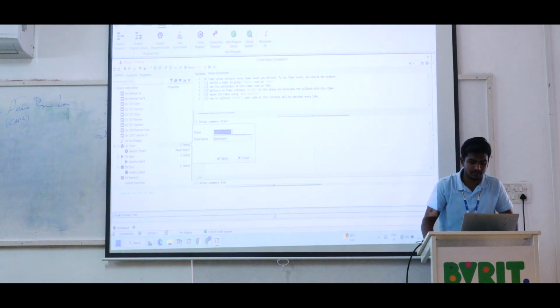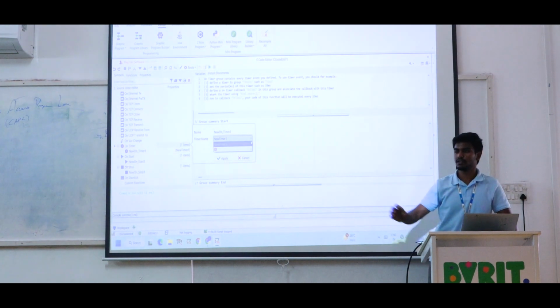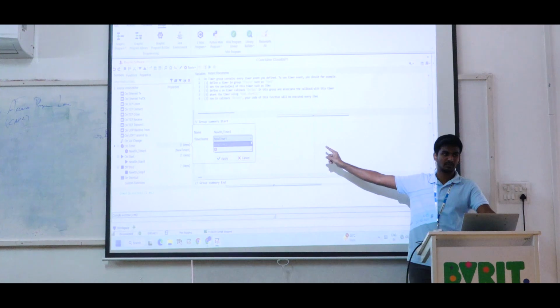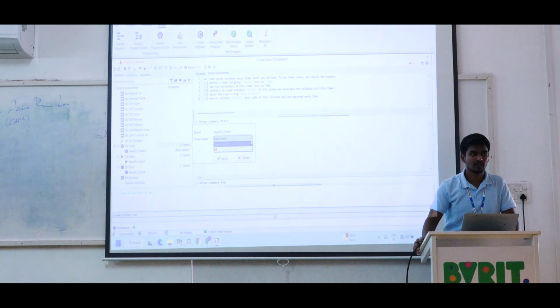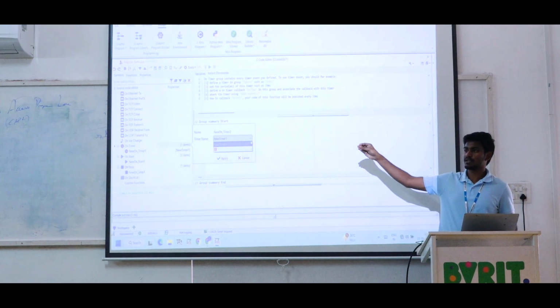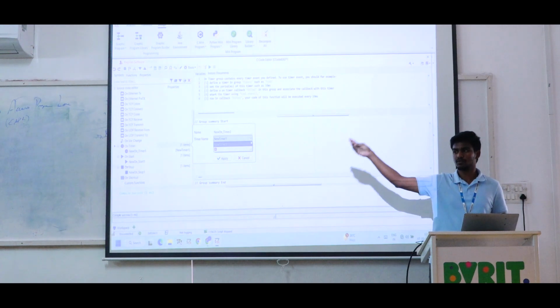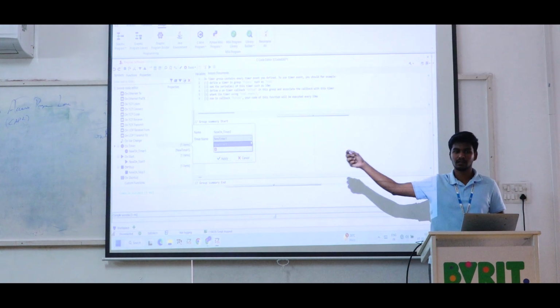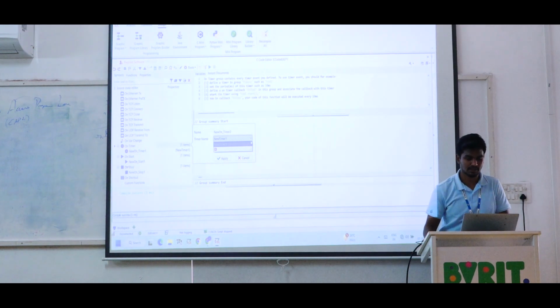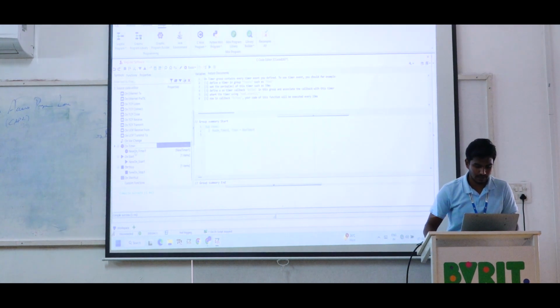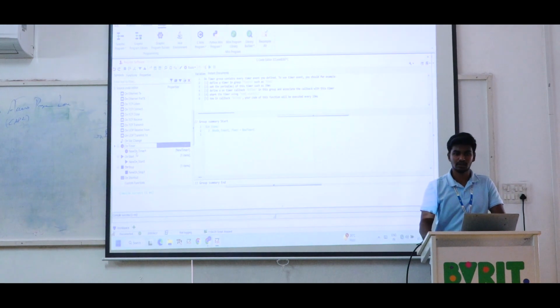It shows some default name. After that, in the second field you have the timer name. We need to select the timer variable we created here. We created only one timer variable, so it shows automatically. If you create different kinds of timers, one for 1000 milliseconds, one for 500 milliseconds, one for 10 milliseconds, you have to select based on that. Now we created only one timer, so just check this and click apply. After apply you get one sub item, new on timer.